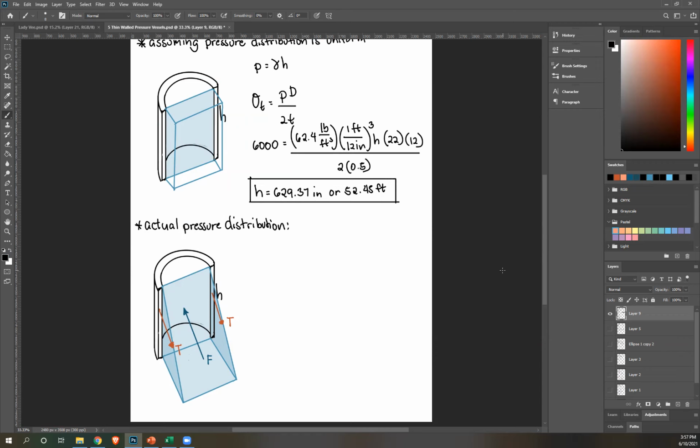And then how do we get the equation for force F? F equals the volume of your pressure diagram. If before, force is just pressure times perpendicular area, now the equation, since again we don't have uniform pressure, is the volume of your pressure diagram. Okay? Great. So let's compute.